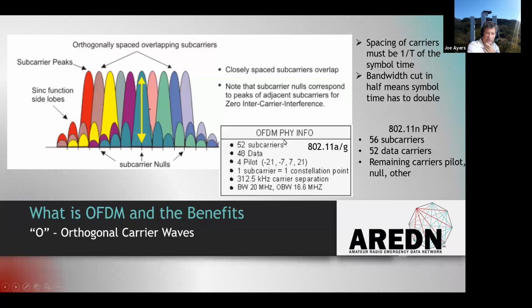Across these carrier waves, with 64 carrier waves, if we look at 802.11a/g, the specs keep evolving compared to 802.11n. They keep packing in more data rates, and even AC goes further in packing in the data rates with higher QAM rates, which of course require a higher signal to noise ratio.